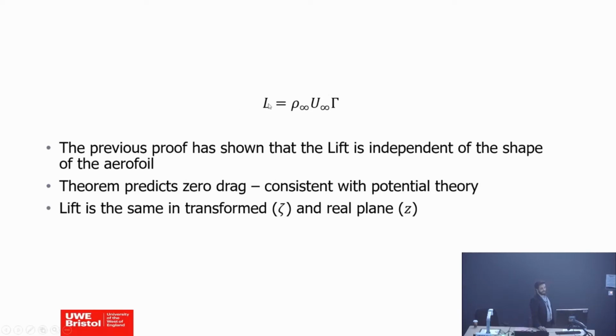So this equation, as I told you, is independent of the 2D shape. So it can be any 2D shape, including cylinders and airfoils. We're more interested in airfoils, of course. Of course, it only gives us lift. The drag is 0 as before, D'Alembert paradox, so we can't do anything about drag. The only way to get drag is you have to have a model of the boundary layer. Otherwise, you get 0 drag.